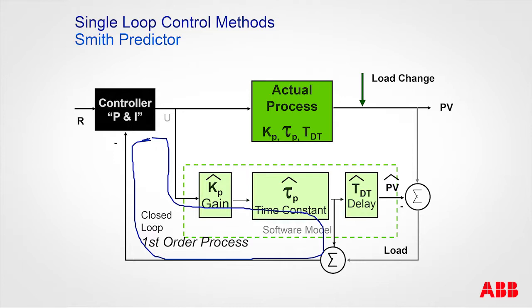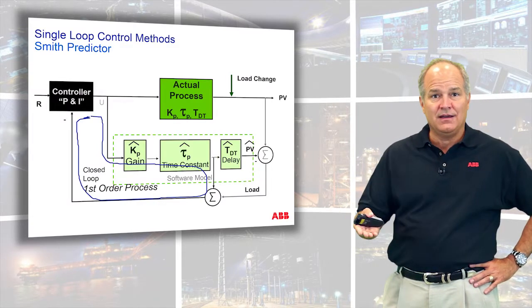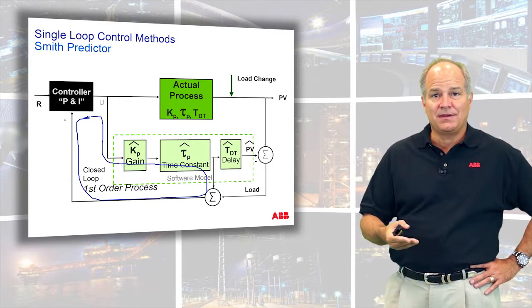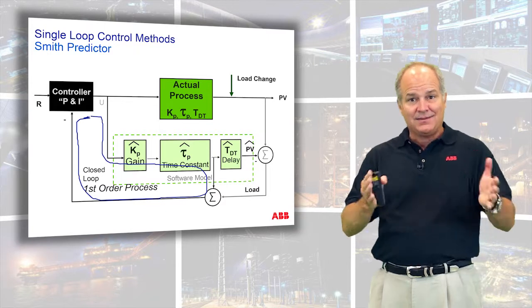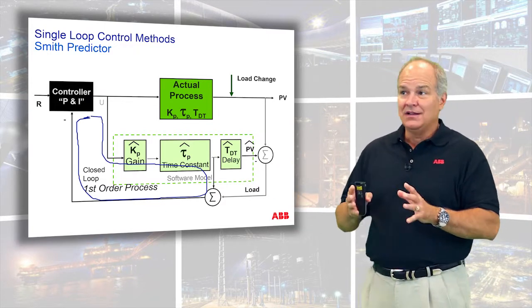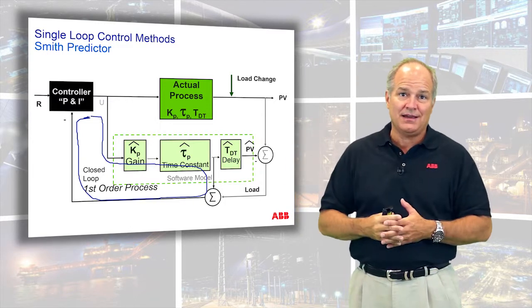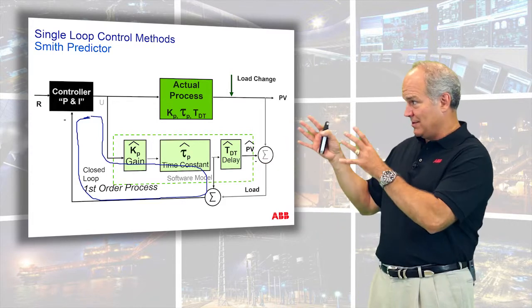It's what we talked about before, where you can use tau ratio, you can use 1 over Kp tau ratio, and your integral time is equal to your open loop time constant. And then you pick the speed of the response, knowing that the dead time's still there, but now you don't get that overshoot. And that's the secret. So when you have long processes and you can't allow overshoot, you can't use a PI algorithm. You have to use a Smith predictor, and that's the beauty of this.